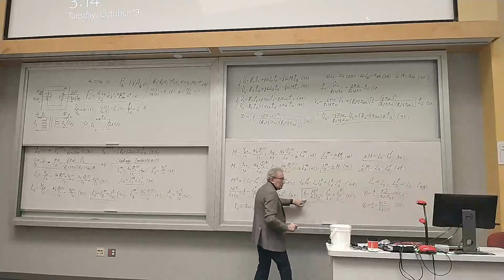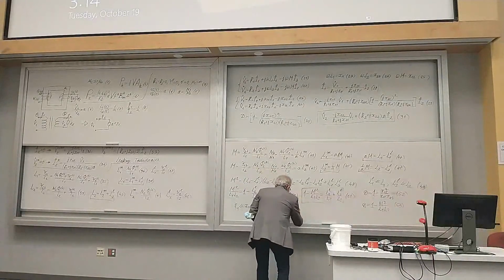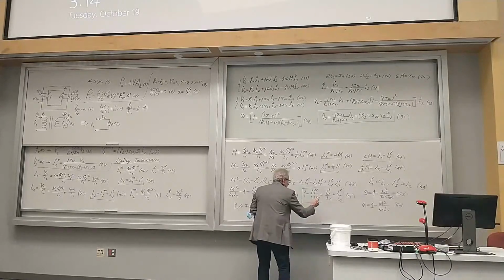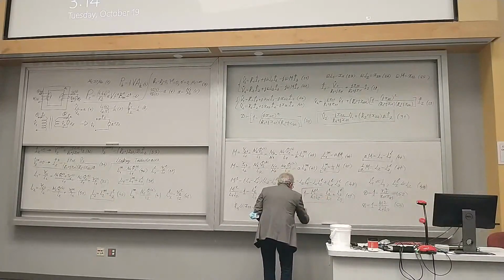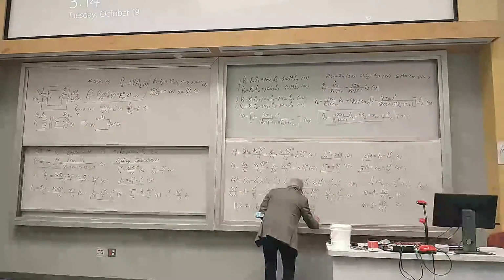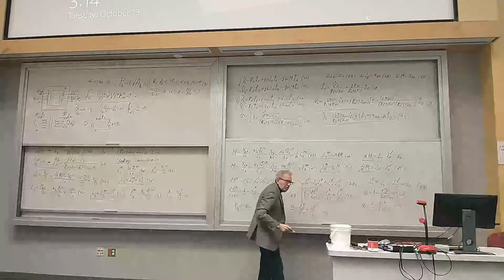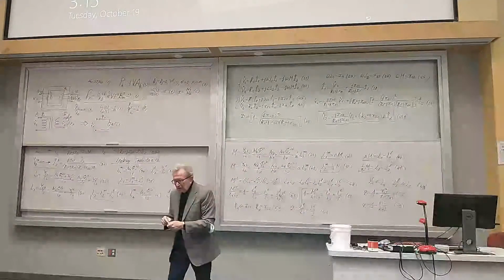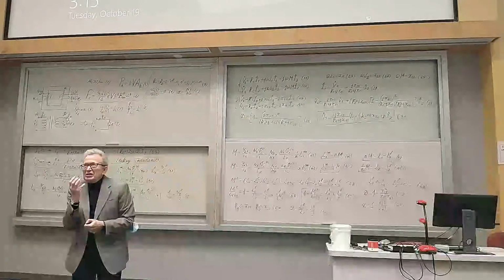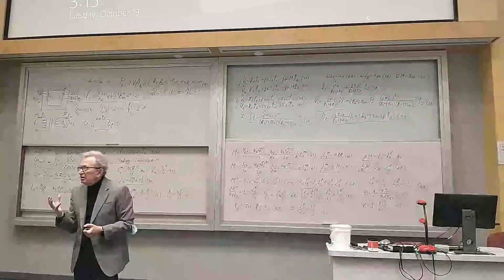And it's equal to this expression. Consequently, D is determined by leakage reactances. So we achieve this result: leakage reactances determine D, and D determines the property of the transformer.